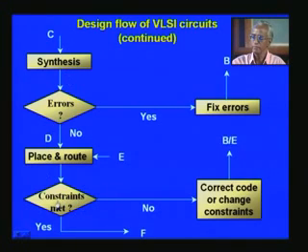So basically in FPGA, these constraints will be the speed of operation, along with the pins that you want to configure. And in ASIC, in addition to this you will have power as well as chip area also available as a constraint that you can program.